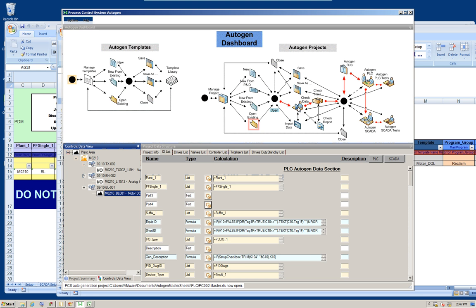When you click on this action trigger, it does a data consistency check, meaning that it would check for a motor that all the I/O points required in order to control the motor in the control system are entered, and all the data in it is entered, and it's consistent and free of errors.